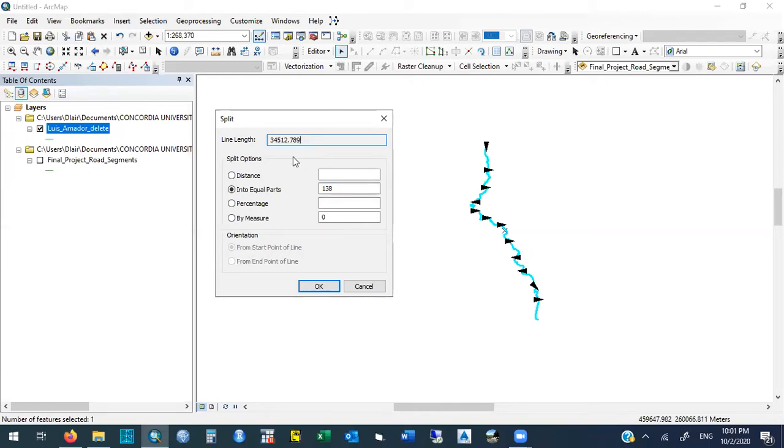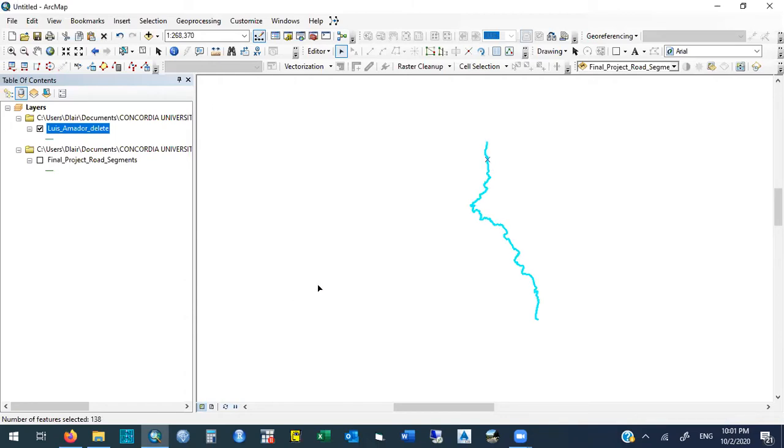You guys are worrying too much about the accuracy of your lengths or how many you have. We are just going to break this into little pieces, and from every little piece we will get the midpoint, and those points are going to be imported in Civil 3D. So if the segment is 99 or 93 or 110, it's not much of a difference, because those points are only going to guide us when we are putting the alignment in the other software. It's only a reference point that we will have. Okay, thank you.